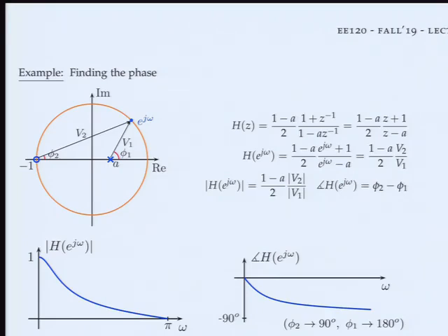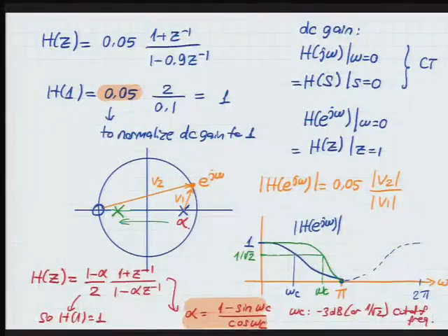So with that, let's go back to an example that's not low pass. Let's do a high pass this time. But again, let's keep it very simple, based on our intuition. The only intuition we're using here is this geometric interpretation of the frequency response: distance to zeros divided by distance to poles. So now my goal is to get rid of low frequencies and pass high frequencies.